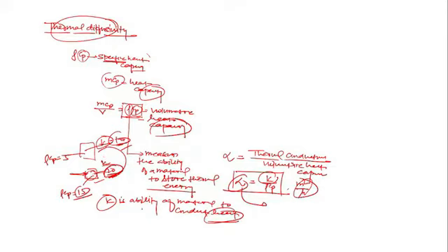But I told you every material has two properties: the transport property, the ability to conduct heat, and the ability to store heat. The storing capacity also plays an important role, and it is more for the second material. If you write thermal diffusivity as K by rho Cp, it is 20 upon 15 here, and 10 by 5, which is 2, here. So the second material will diffuse heat at a slower rate than the first, although its thermal conductivity is more.